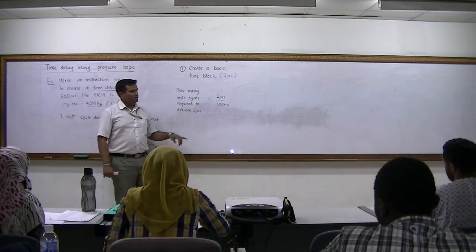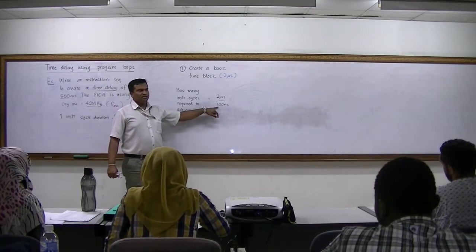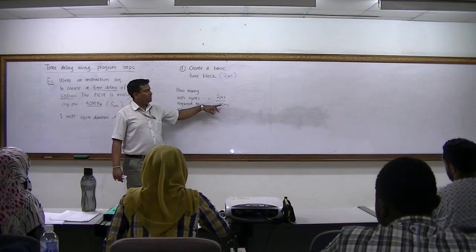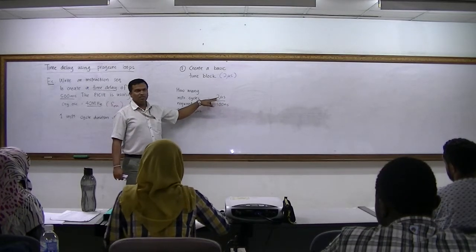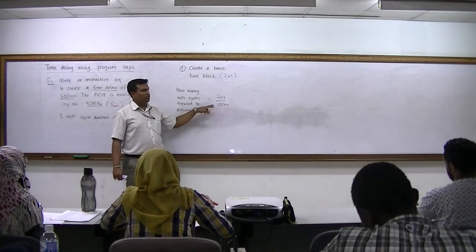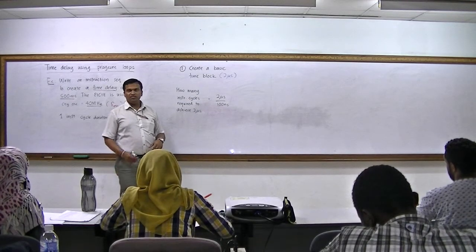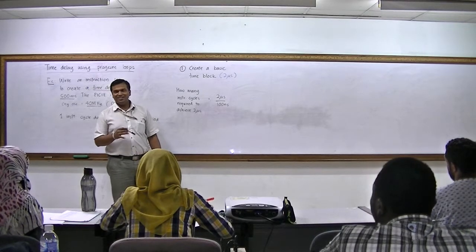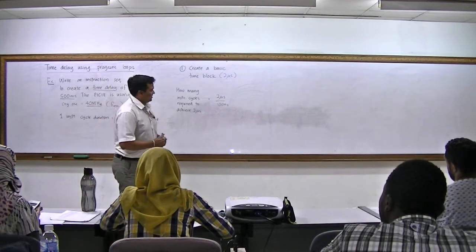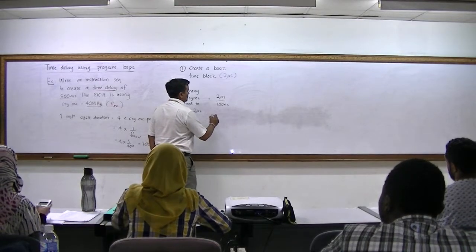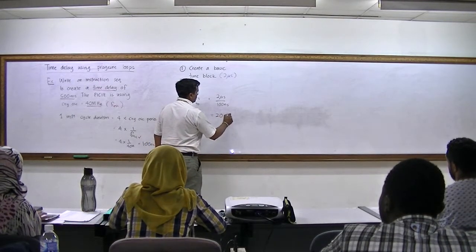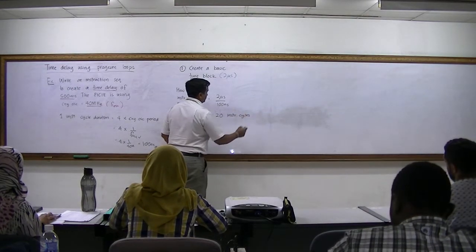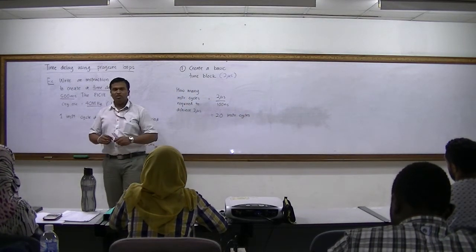Quite a simple thing, right? If one instruction takes 100 nanoseconds, to find out how many instruction cycles you need, just take the time that you want and divide by 100 nanoseconds. You'll get how many instruction cycles you need, right? Don't worry about writing. Understand what's happening here. So how many instructions do you need? 20 instruction cycles. Do you all get the same number?